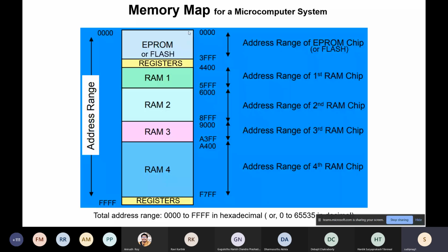Typically microcontrollers offer you certain memory space like 2 kilobyte, 8 kilobyte, 32 kilobyte, 1 megabyte. Those kind of memory spaces are allocated for flash or non-volatile code storage. So that is reserved from 0 onwards. But this notion of 0 onwards for code actually breaks in certain microcontrollers. I cannot say that this is true for each and every microcontroller. It is true for most, many microcontrollers which are in the 8-bit and 16-bit space.